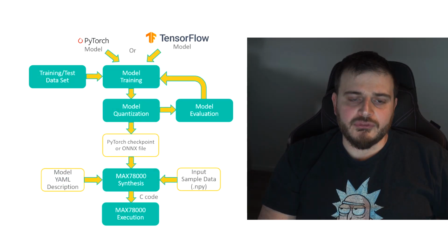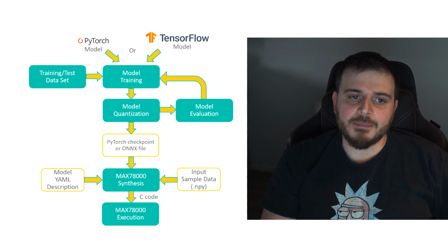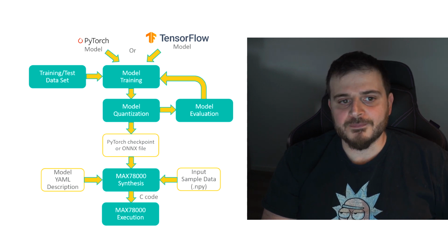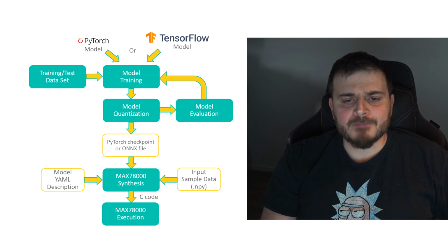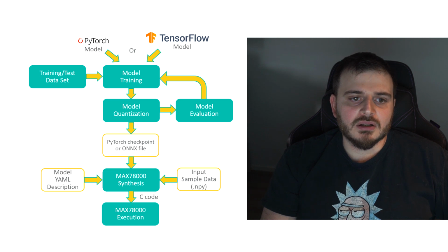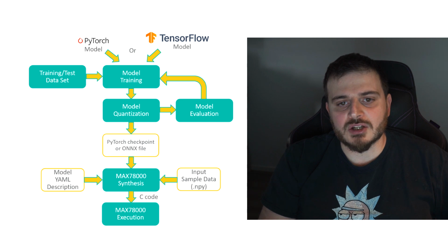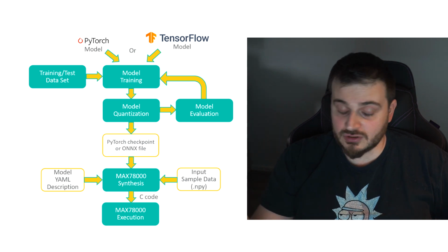The development flow of this kind of project on this platform can be summarized in three phases. A PyTorch or a TensorFlow model is created with a series of well-defined subclasses in order to reflect hardware capabilities. This model is trained using floating point weights and training data. Weights can be quantized during the training phase or even after that. The result can be evaluated to reach the target in terms of performance, such as accuracy, recall, and precision.